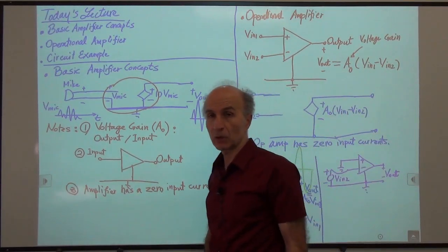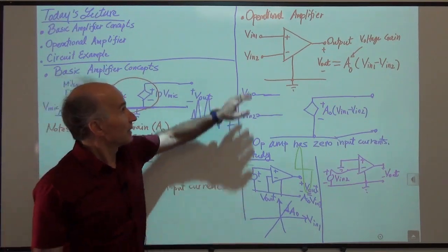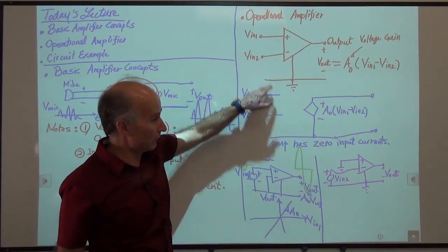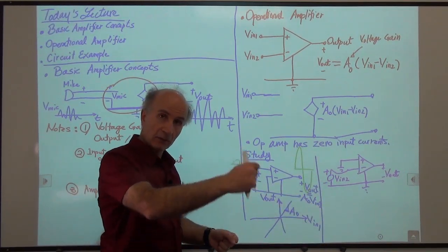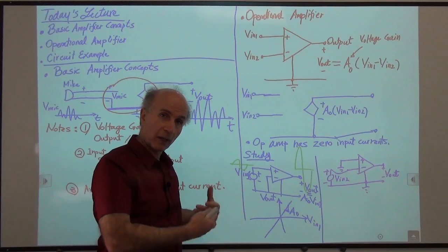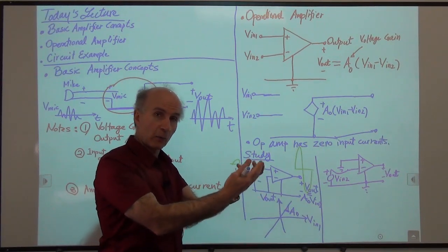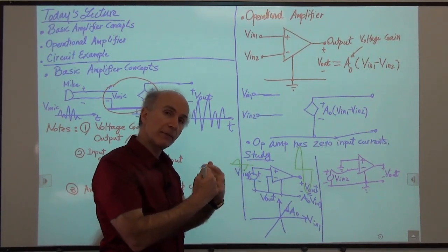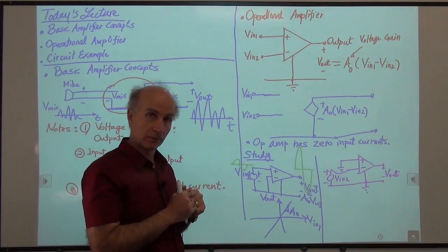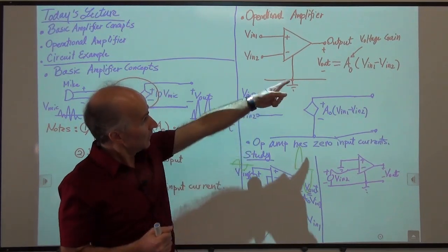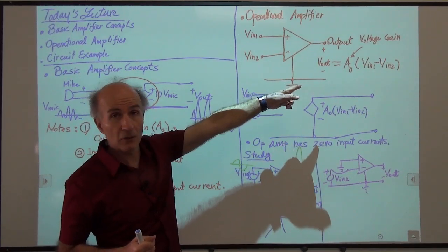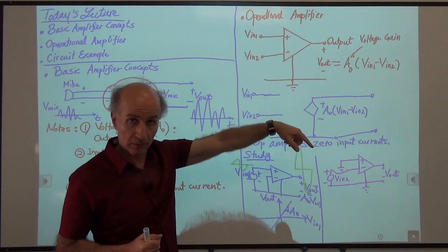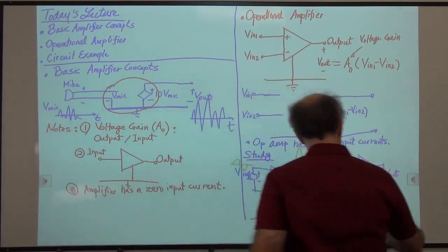All right? So all I've done is V in 1 is set to 0, V in 2 is driven by a voltage source. And again, I'm varying V in 2, I'm sweeping this value from minus infinity to plus infinity, and I want to plot V out as a function of V in 2. So how much is that? You go back to that equation, V in 1 is 0, so V out is just A0 times minus V in 2. So the plot is pretty straightforward.